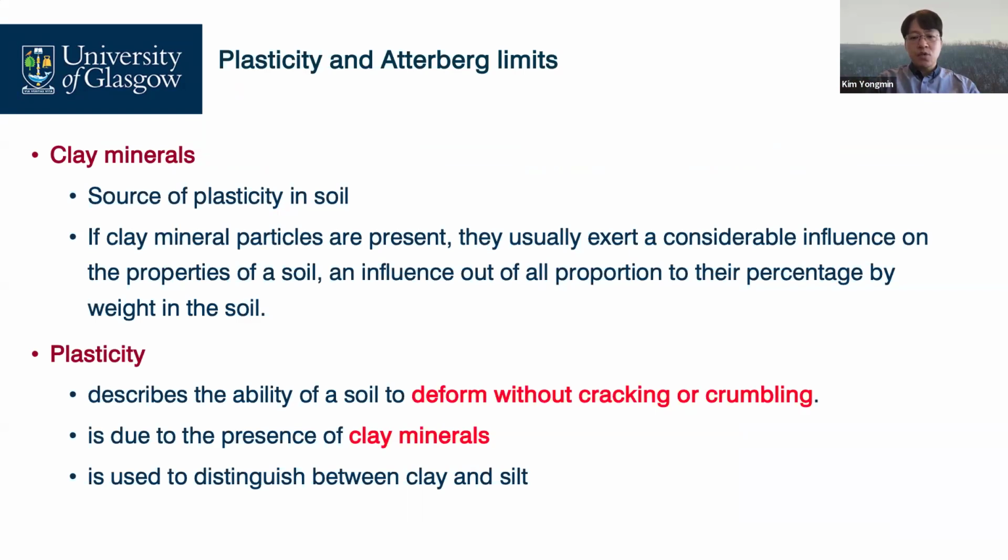Clay minerals are the source of the plasticity in soil because the clay contains some water due to their mineral structure, right? Gibbsites and silicates are repeatedly stacked up, bonded by different types of ions, with a large specific surface. So in other words, clay attracts water on the large specific surface.